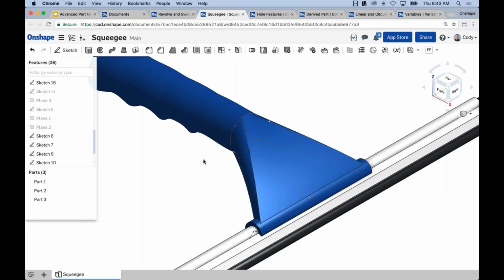So I will say in many situations, they both work identically. But if you don't have an end point to end point scenario like I did, and you have a curve passing through the plane, that's where you'll use Pierce. Coincident wouldn't work in that scenario where you have a helix passing through the plane and you want to attach the center point to it. Many times they both give you the same end result, but there will be times when you're creating more complex shapes where you're not attaching to the end of the curve, but to some point where the curve passes through the current sketch plane. And I think that's where you'll use Pierce. Forgive me for the long explanation there.